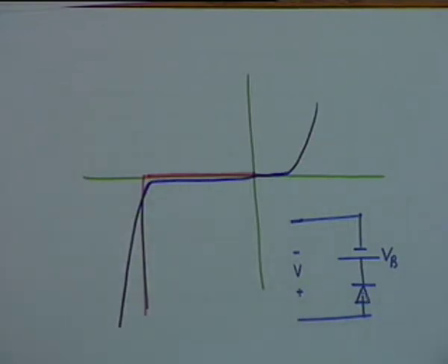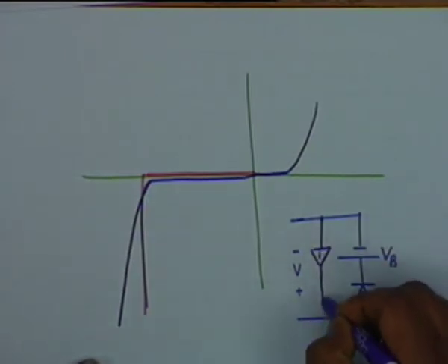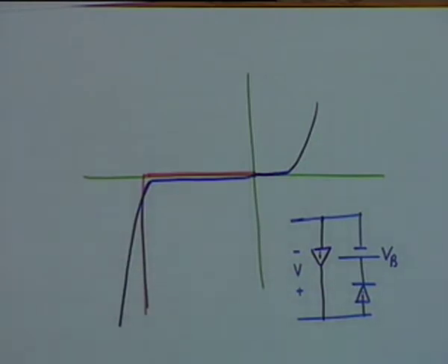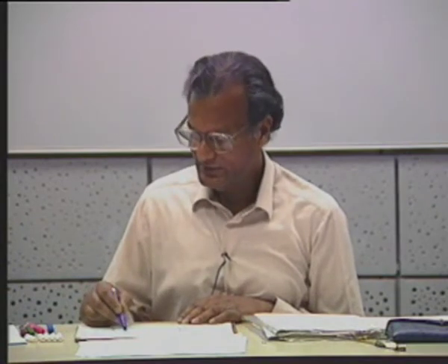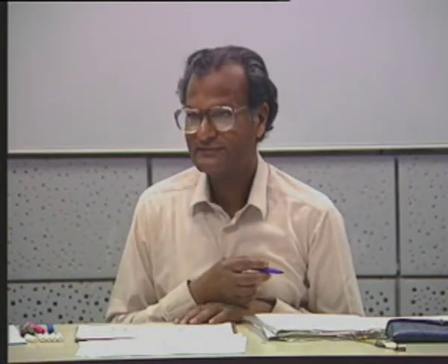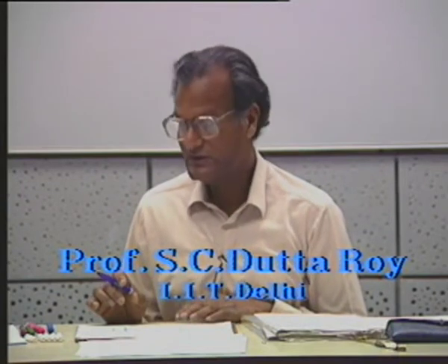After that, if it is the red curve, then we have approximated it by an ideal diode. Now, if you want to include its behavior as a normal diode, obviously you should put an ideal diode here, or an ideal diode in conjunction with the threshold voltage, RD, reverse saturation and all that. Now, since we are not using a Zener diode in the normal operation, we can forget about this. Is that clear? We are only considering the equivalent circuit when it is used in the Zener mode of operation.